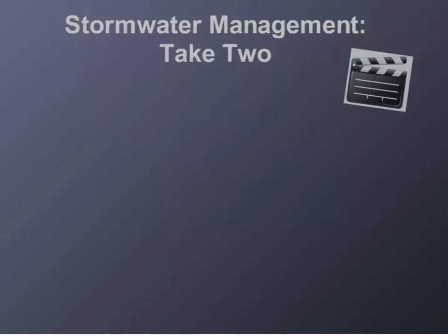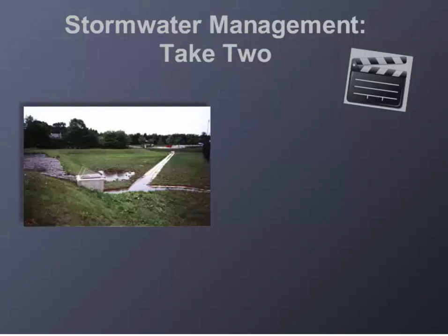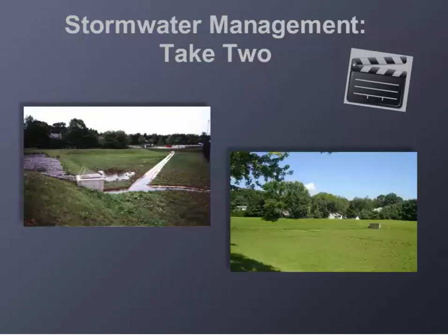Then, from the mid-1970s through 2004, detention basins were the preferred solution to capture runoff, detain it, and release it slowly to the river. The idea was to hold the water and let it out slowly, reducing the flooding impact that earlier approaches caused. Detain peak flow during large storm events, reduce downstream flooding during major storms, and use concrete low-flow channels to minimize erosion, reduce standing water, and quickly discharge low flows.